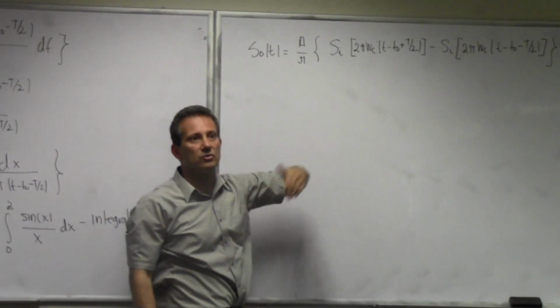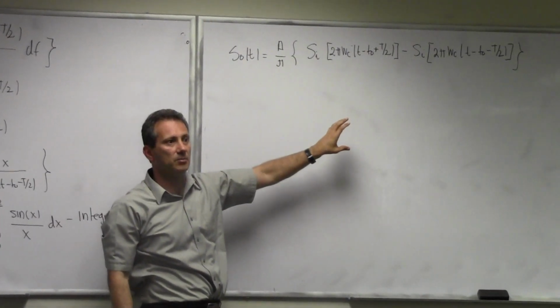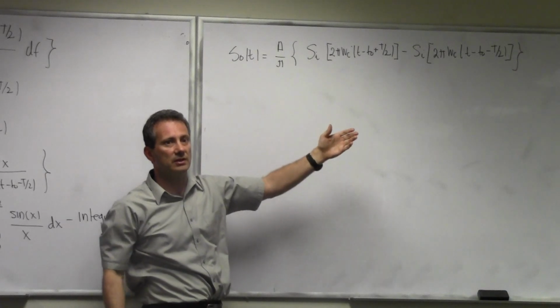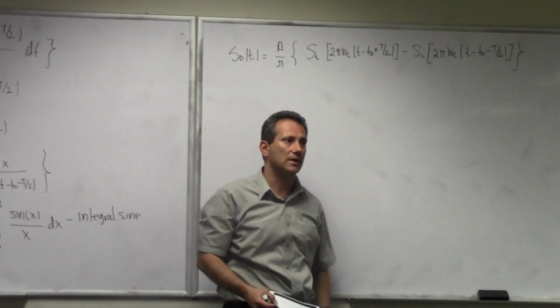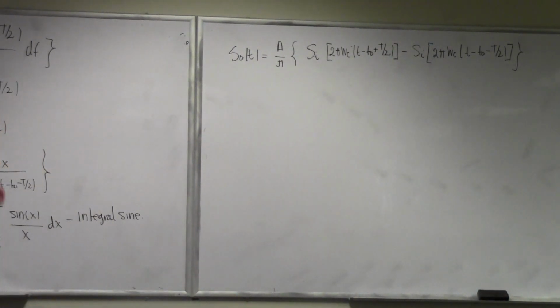T0 is the delay introduced by the filter. So in terms of shape of my pulse that comes in the output, T0 doesn't change anything. It just changes how far to the right this pulse is going to be. How much is the delay through the whole system.